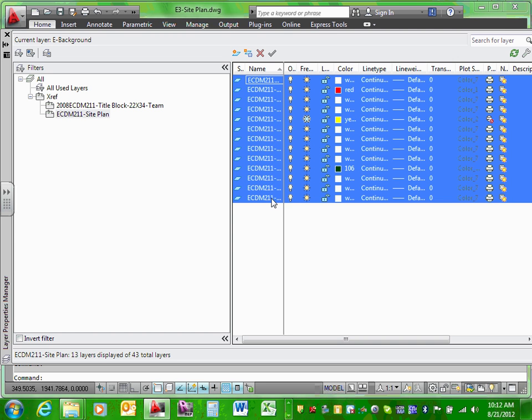When you guys get there, can you give me a thumbs up? But before you do that, here's what happened in the past. I want to make sure that you are clicking here, not at the top, not here. If you click here, you make all your layers color 8. We have to start over. This is very essential, guys. A lot of students click on the A at the top, and they make all the layers that they have gray. We don't want to do that. Can everybody make sure that you are in the site plan and you're only looking at these layers associated with the background? Can I have thumbs up?